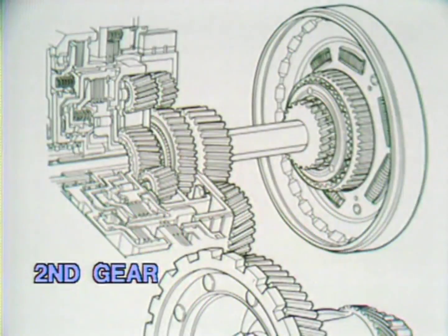To begin our study of second gear power flow, let's go back to our clutch and band application chart. In second gear, the low and intermediate band stays applied, and the intermediate clutch is applied. On the graphic, we can see what happens on the 1-2 upshift.